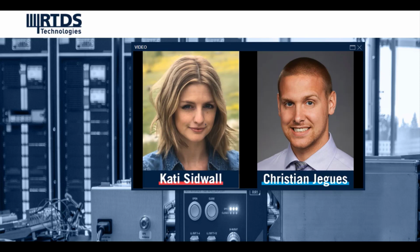And it's that card that actually exchanges the binary inputs and outputs with the test interface and with the IntelliRupter. So when the IntelliRupter is sending commands to the RTDS to perform things like the pulse coding, those binary signals are being sent out of the Omicron RI-R1 and brought into the RTDS using the GTFPI card.